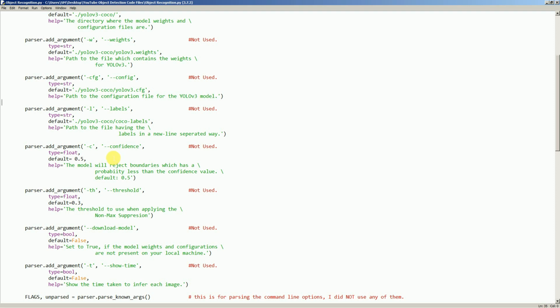I should mention here again, I'm sidebarring. When you start trapping for these indexes, you can only send data down the serial port because I'm running the GUI and I'm running the webcam. I can't use the serial for output from Arduino.